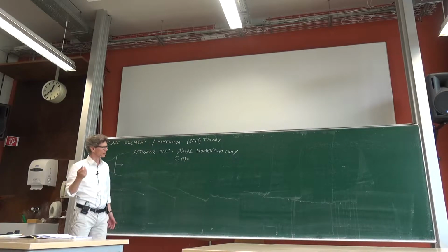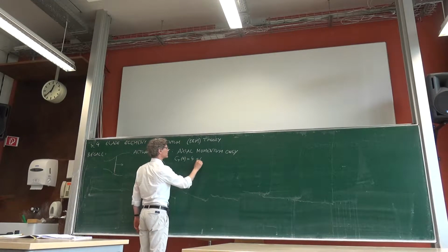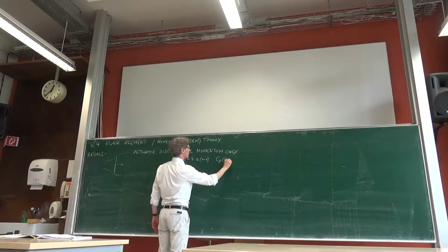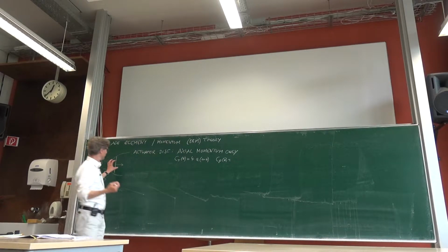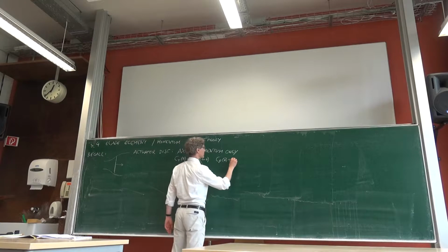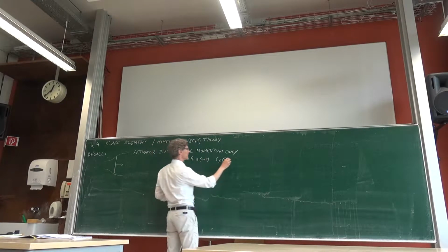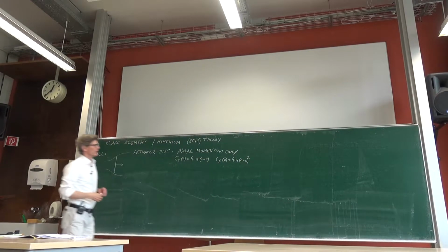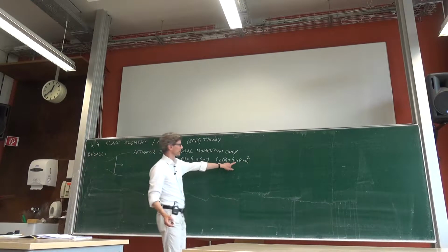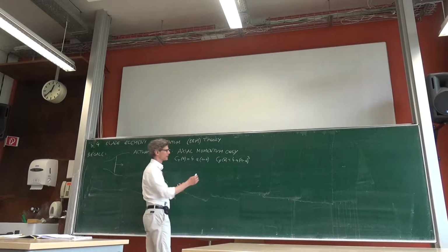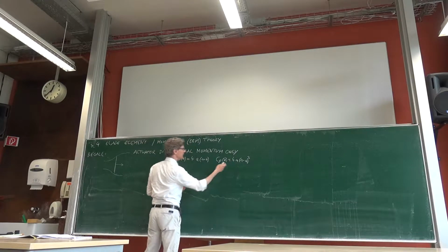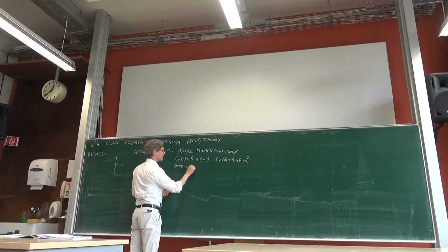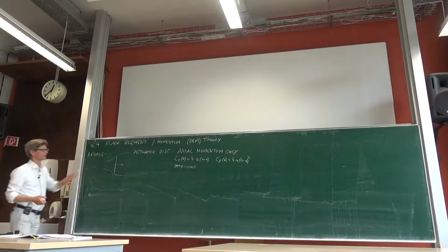You remember maybe the formula. I think it's useful to remember it because we used it so often. We also derived the power coefficient, which was actually the thrust times the speed of the wind at this location, and that is actually this formula times 1 minus a, to the power of 2. And we could also maximize this value with respect to a, and then you remember the optimal value of a was 1/3, the induction factor, and then we could derive the Betz limit. So this was all based on axial momentum only.